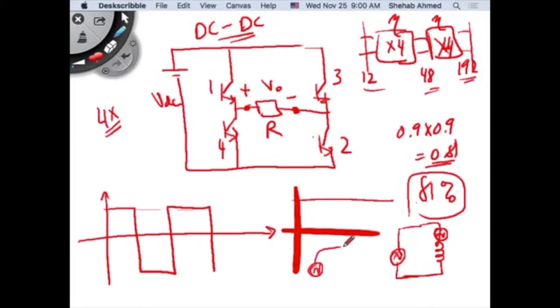Then you're placing a voltage source across a piece of wire, basically. So the resistance of the wire will limit the current. That's it. So you're going to be pushing a huge amount of current through, and you saturate the transformer. It's useless. You're not building a transformer anymore. You're building a heater.